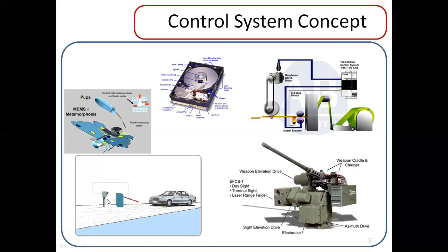Here, I will first explain this particular system as an open loop, and later on I will explain the same system as a closed loop system also. Considering the same operation that you are visualizing on the screen as an open loop control system, when the sensor senses the car, it gives the signal to the gate that it has to be opened. But there will not be any feedback to the control system as to whether the gate has been opened or not. So it may get opened or may not get opened, or it may be fully opened, or only semi or 50% of the gate will be lifted up. That doesn't matter in the case of an open loop control system.